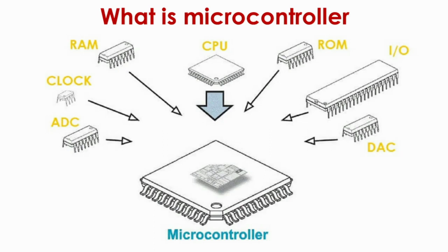So before we go further, as I said, Arduino Uno has Atmega 328P microcontroller. So it is important to know what microcontroller is. It is a single chip, that is integrated circuit. It is a chip or IC which has everything on it, like CPU, that is central processing unit, random access memory, RAM, read-only memory, ROM, then ADC, analog to digital converter, or DAC, digital to analog converter. All these functions are packaged onto a single chip, single microcontroller, and that's how the microcontroller functions.